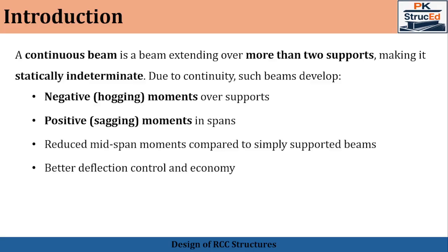Now, what does a continuous beam mean, sir? It's a beam that extends over more than two supports. Because of this continuity, the beam becomes statically indeterminate. So, unlike simply supported beams, internal forces in continuous beams cannot be obtained using equilibrium equations alone.